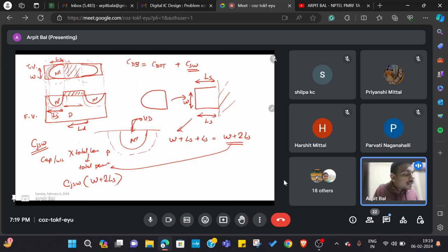And my problem is the diffusion region is actually entering into the channel. If it starts entering into the channel, it means it is basically forming the channel, which was supposed to be formed only after a particular gate voltage is applied, right?